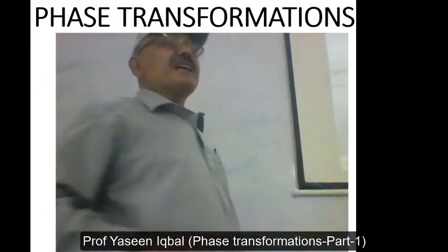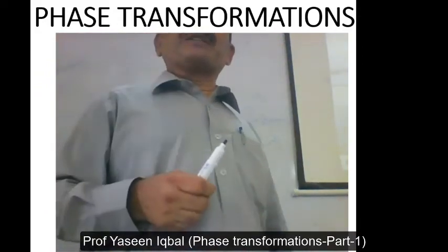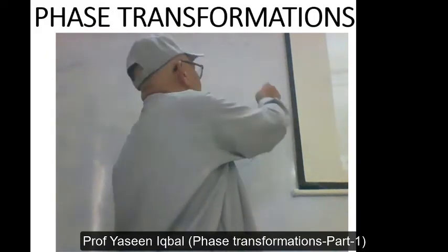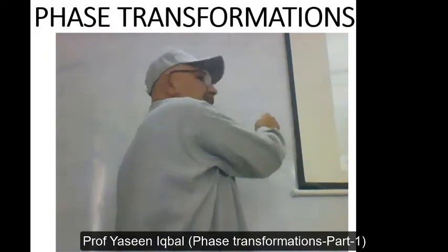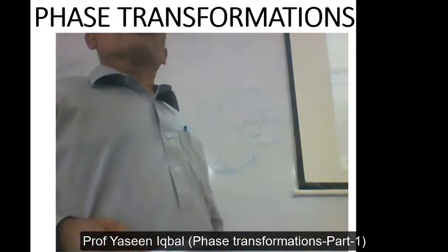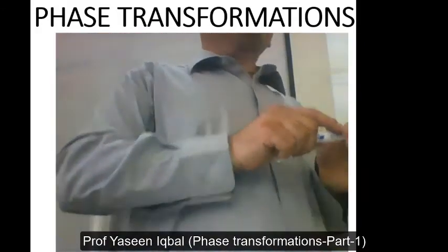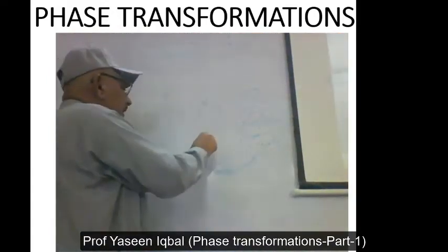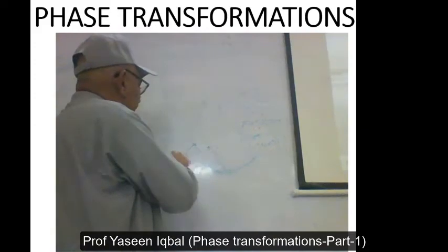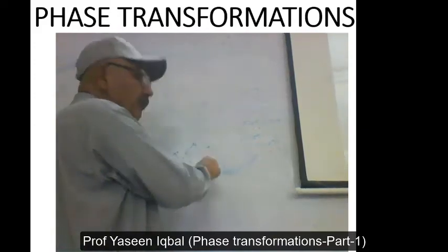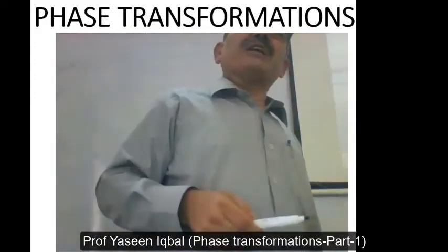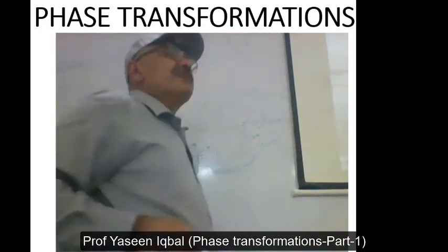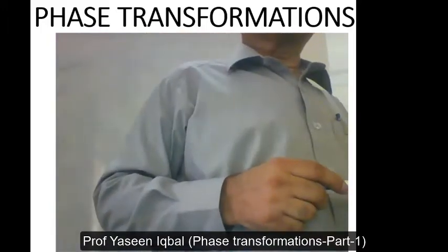This phase is melting at relatively lower temperature. This phase is melting at very high temperature, and this phase is melting in between the two. So when you heat treat the material, you partially melt the material. The material was particles like this, and these pores and voids were causing permeation of the liquid. By partial melting, you filled these pores, and the material became impermeable.